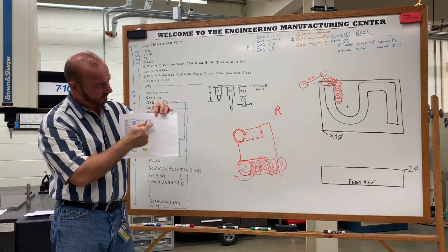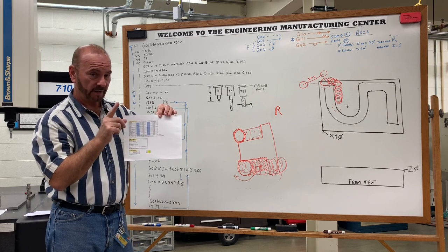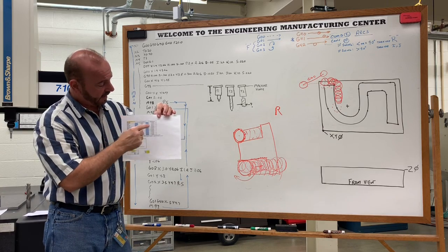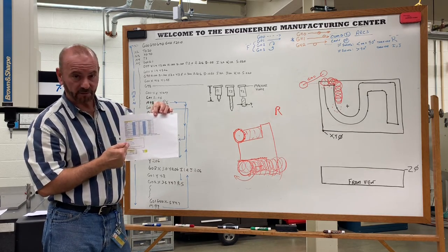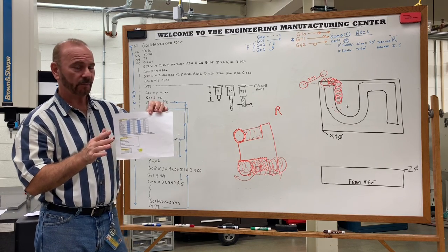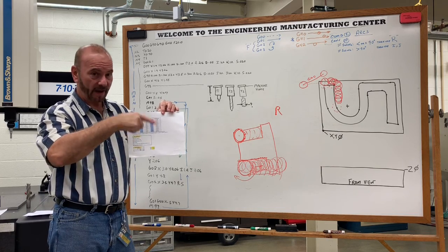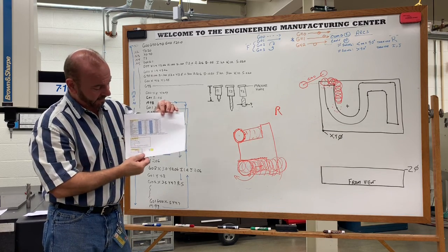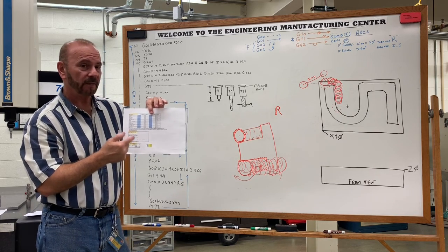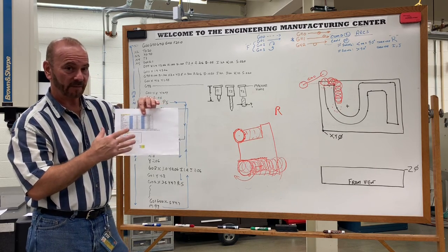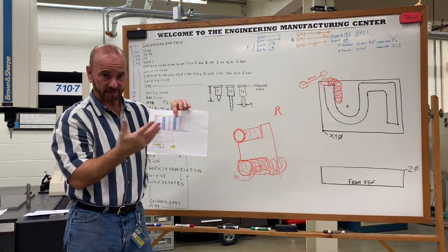And we have these two columns here. One is called surface feet per minute, which is also abbreviated as SFM, and feed per tooth, which is also abbreviated as FPT down here in the formulas. So the first thing you always want to calculate is the RPM, because that's going to tell you how fast to spin the cutter. And then you're going to use that RPM that you calculated in the inches per minute feed rate, which is exactly what it means. It's how many inches that cutter will travel per 60 seconds, every minute.